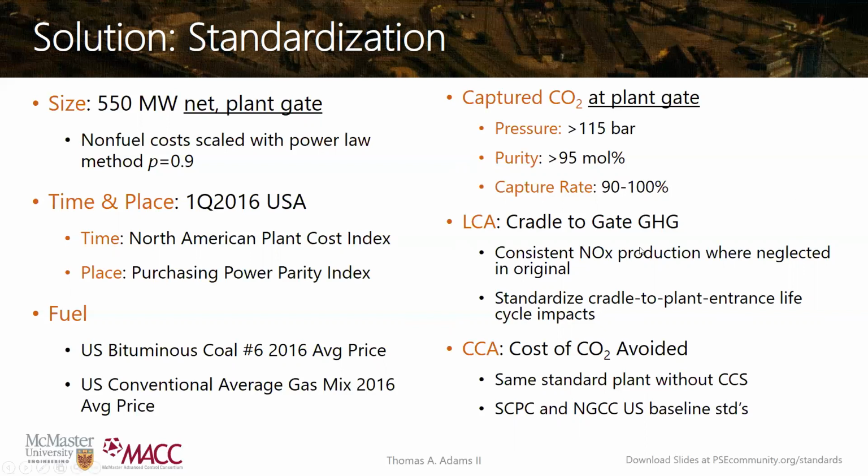Standardizing how much CO2 is captured. One of the big problems is that with a lot of these studies, they'll say they capture all the CO2, but they captured it at 1 bar. That's not useful. I need to get it up to pipeline purity. So we have standardized the pressures and the purity and the capture rates, making sure that everything is like to like.